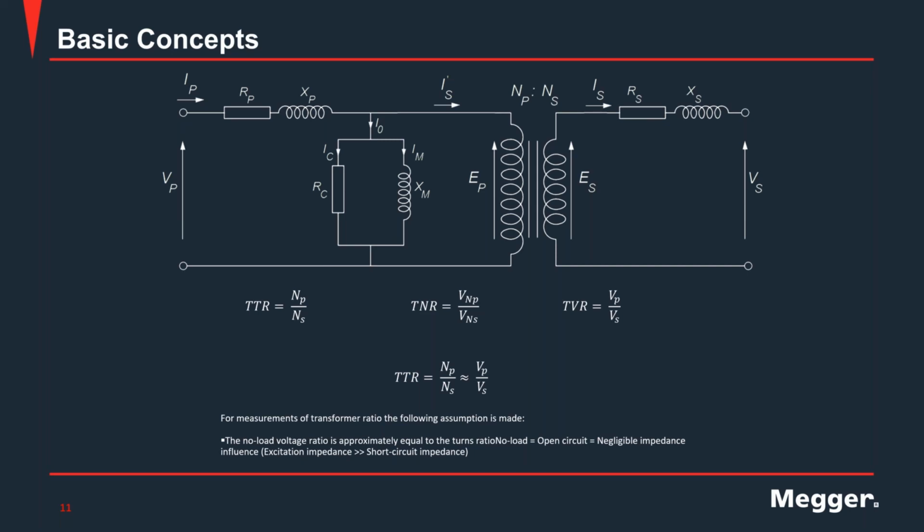That is not something that I will find on the nameplate or on the maintenance manual of the unit. Again, typically, as end users or the individual running the test, I don't know that number of any transformer. So what we are actually measuring in the field is the transformer voltage ratio, the TVR, indicated on that last equation on the right. And then I compare that measurement towards the transformer nameplate ratio, which is the ratio that I calculate from the rated voltage values for each winding of the transformer, and I take those from the nameplate, hence the name transformer nameplate ratio, right?